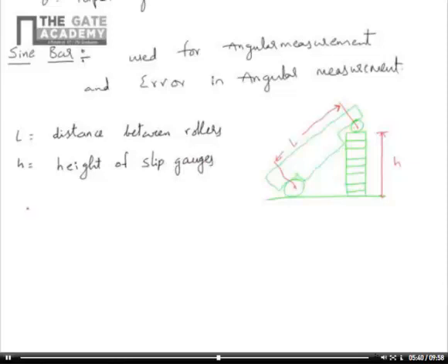If you want to measure the angle here, where theta is this angle, sin theta equals H by L, that's why it is called a sine bar.